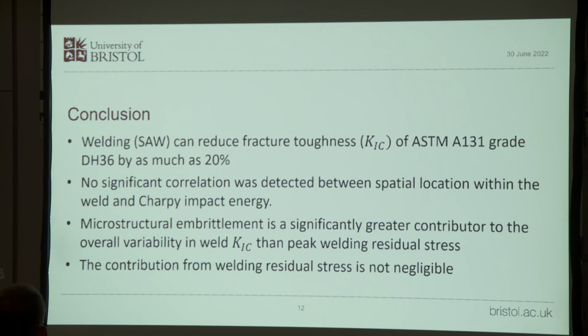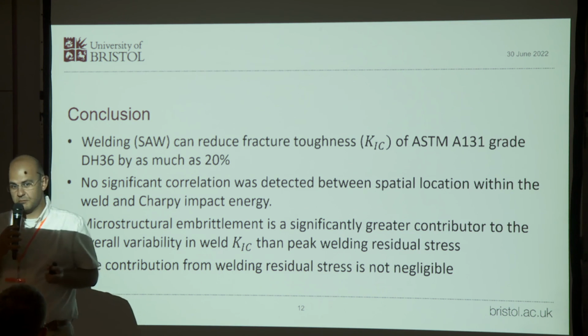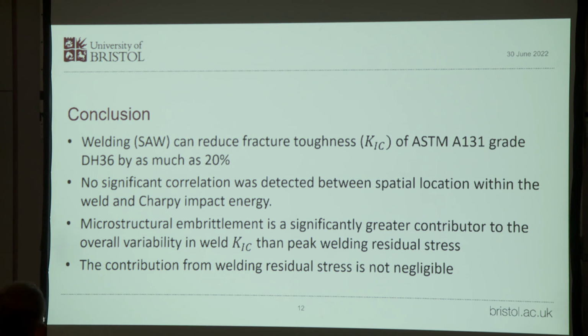So what I wanted to conclude is, when we are welding, we are changing the microstructure and we are putting the residual stress in. Surprisingly, even without these fancy new automated techniques like electron beam welding and laser welding, the guys with the sticks are really good. They very consistently weld things. So the residual stress variability in your weld is not much. However, the variability in the microstructure is a lot more. And the fracture toughness variability that is important for our probabilistic assessment of our nuclear power plant is dependent a lot more on the microstructure than on the variability in the residual stress.